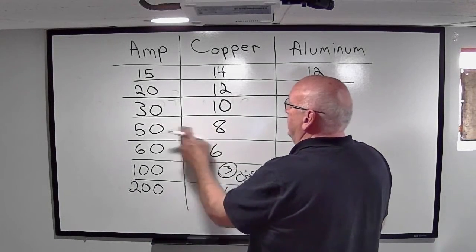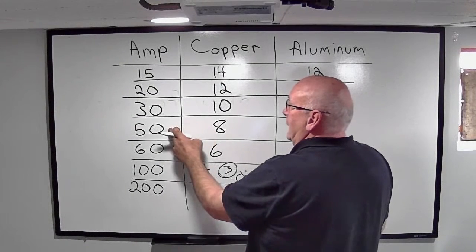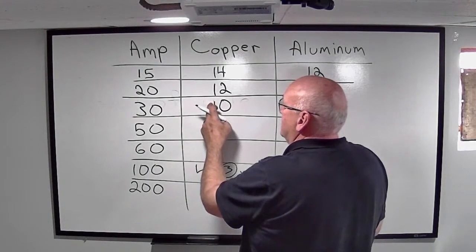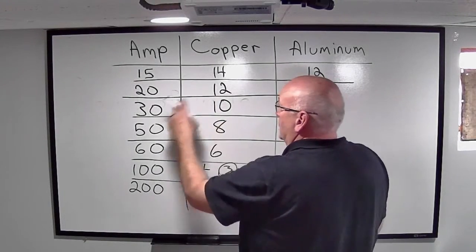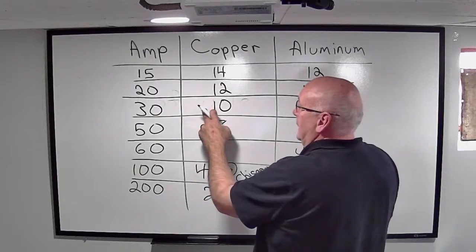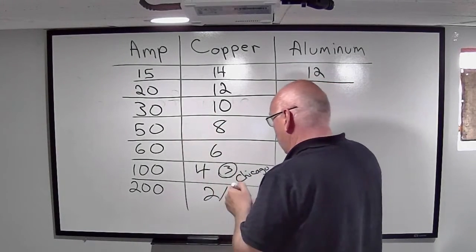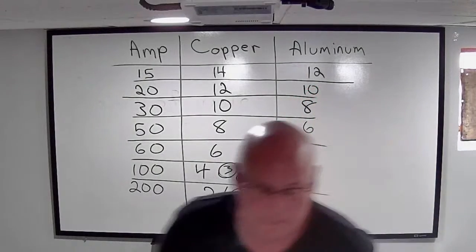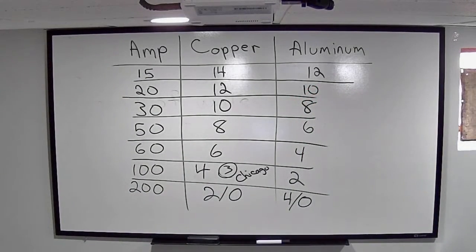Whatever breaker can protect that, that's what I can go ahead and use. So I'm going to go back to the slide drawing in a second, and that's at 125%. But if I had a number 10 copper wire on a 50 amp breaker to go ahead and protect everything.